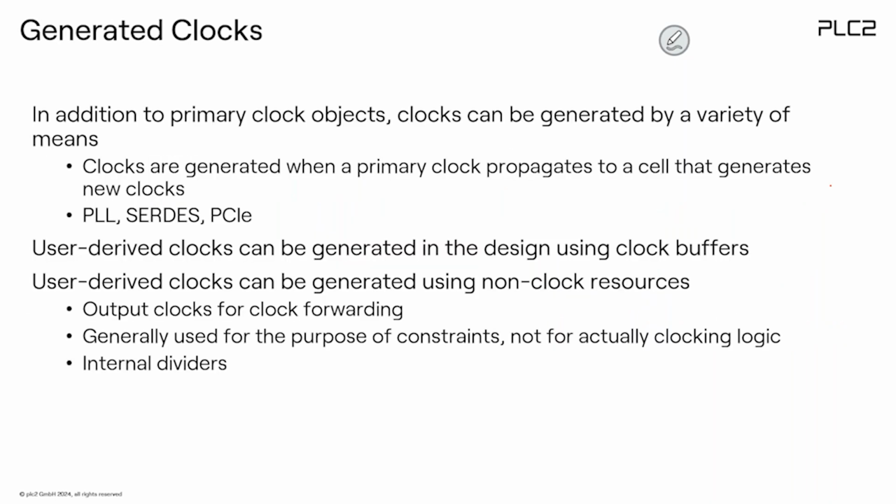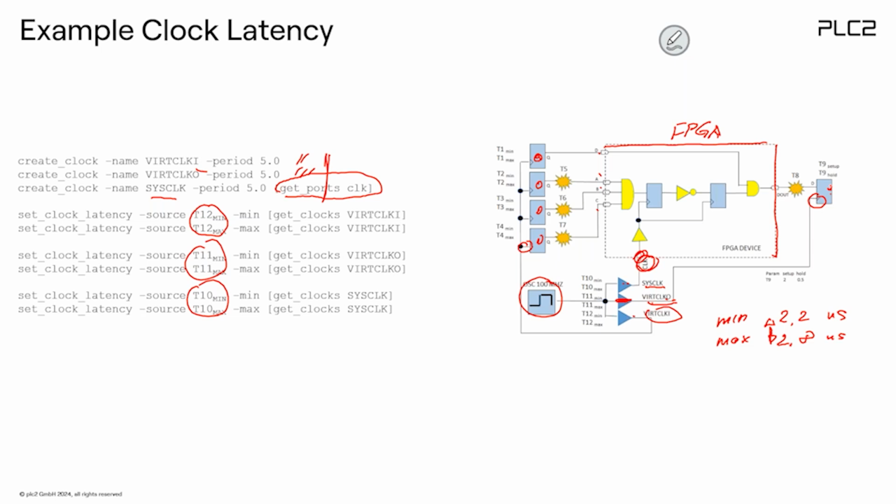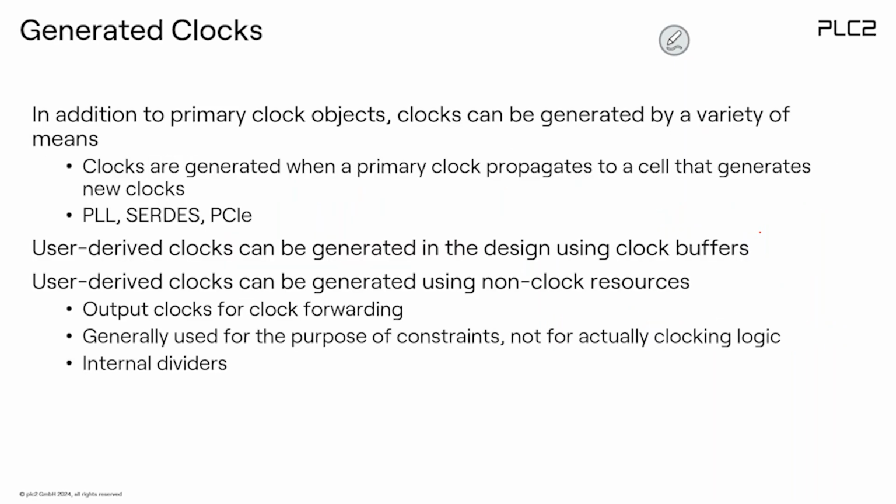And the next one is generated clocks. So what's a generated clock? Usually, if I go back here, it's something like this. We just have a clock which is basically connected to my FPGA. So it's connected and is used somewhere. But in some cases, we would need to generate a clock internally, maybe with an object connected here, which again generates maybe a clock X for some reason. So this means that's an internally generated clock. Now I need a way to define this clock, because it's a clock. So I have to specify it. This is called the generated clock.